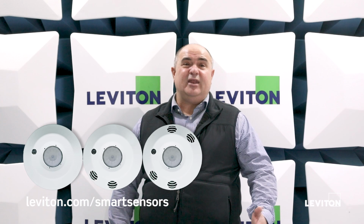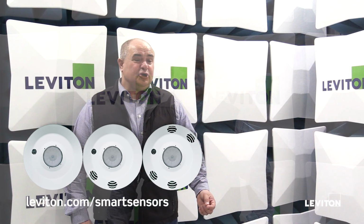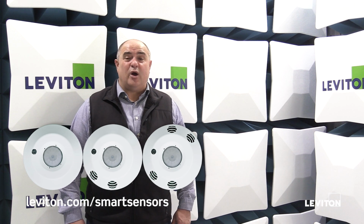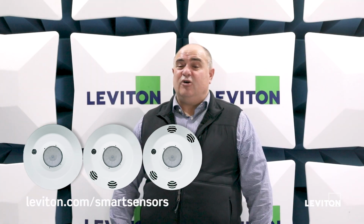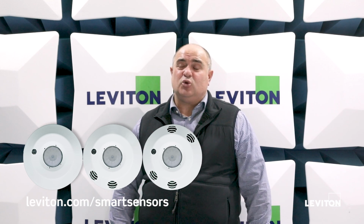And again, meeting that occupancy sensing, vacancy sensing. Having the 0 to 10 volt dimming ability with the smart room controller solution. And also having the partial on and partial off requirements met with the smart room controller. And then daylight harvesting also with the smart room controller. And then how about the switching abilities of the ceiling mounted sensor? Well,